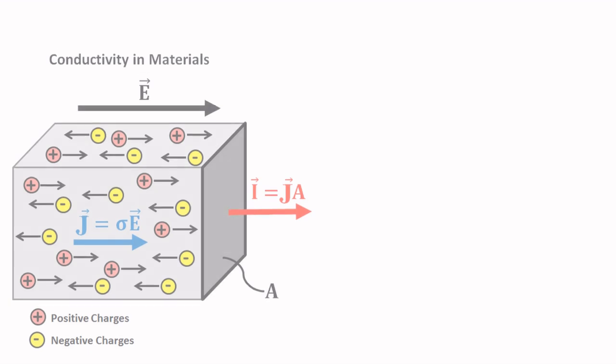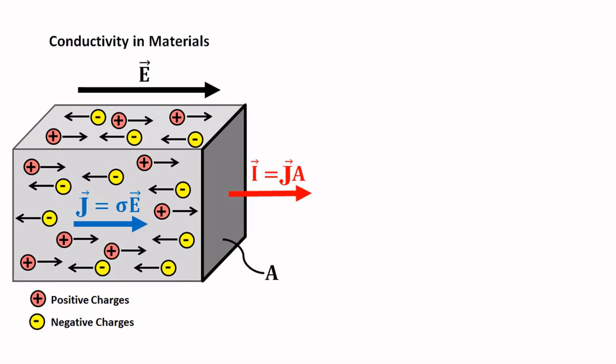When you take some examples, certain minerals like pyrite are very good conductors of electricity, and many other ores which are present in the rock, which are having some minerals, have low conductivity, and non-metallic minerals are also bad conductors of electricity. So when we are passing a current into the ground through the resistivity meter or any kind of source, the ground will distribute the current itself according to the conductivity of the rocks and the minerals that are coming under the influence of the current.